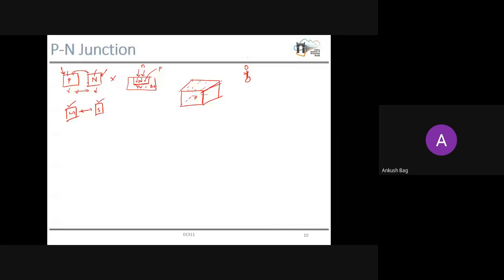So every time we attach another material or another device to this silicon, this problem will arise. In the case of a metal-semiconductor junction, we do not have any choice, we need to take the metal and semiconductor separately and connect them. So at this interface, there will be a lot of dangling bonds, and those dangling bonds will eventually create some surface states. These are called surface states, and these surface states will create a lot of unintentional problems.